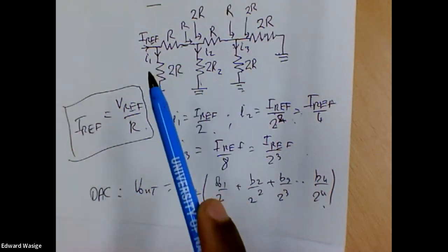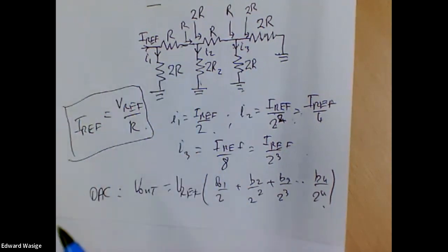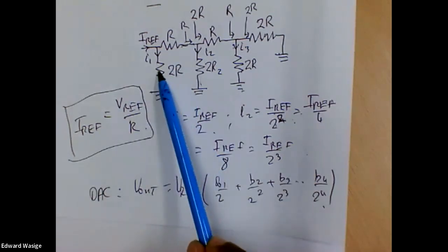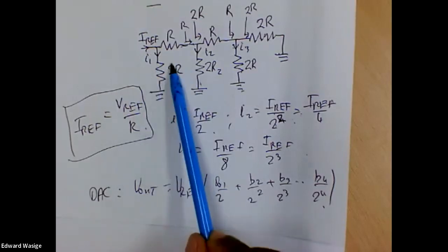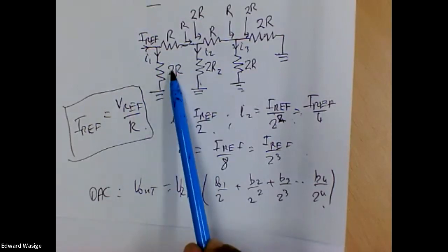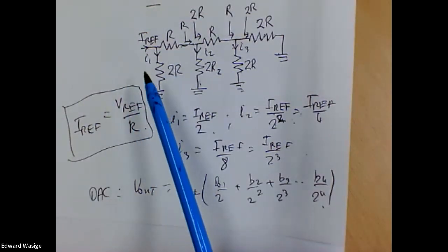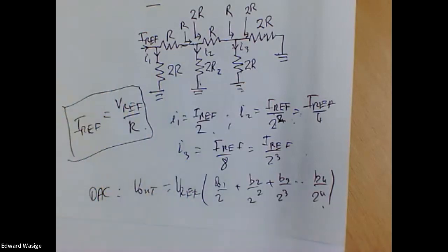If the resistance is very high, then sizing becomes a concern. So we want a good size, and we want the current not to be too high. It would be in the kilo ohm or hundreds of kilo ohm range. Too low, it will consume too high currents.